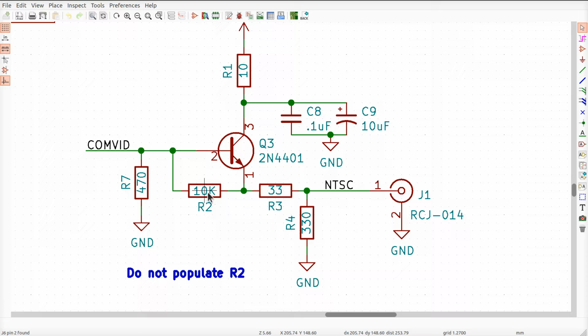Now, maybe the size on this resistor was wrong. I don't know. I mean, you could put a small resistor in here, maybe this was 100 ohms instead, right? Because that's closer to 470 as it goes through here. But that's not really an emitter follower. I'm not sure what this is. I don't know what R2 is for. Okay, I don't really know. So I'm going to stick in a 470 to ground.